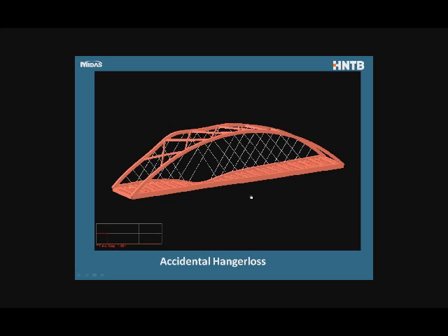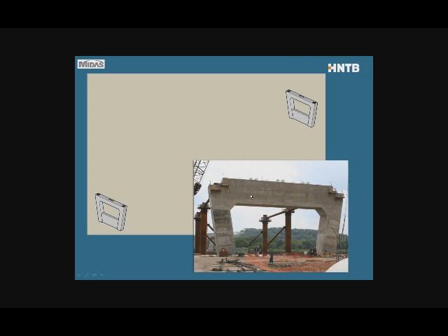You can see how the arch reacts, and this was the portal bridge, so it's a railroad bridge, and that accommodated loss of 3 hangers quite comfortably. So you can see another resiliency in terms of the sudden hanger loss. So we have multiple advantages in stiffness, in bending moments, as well as in the behavior under these extraordinary loads.